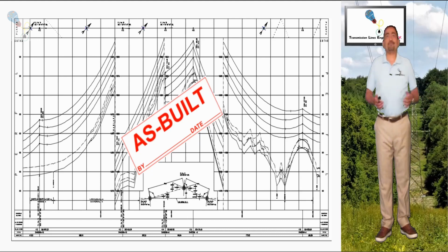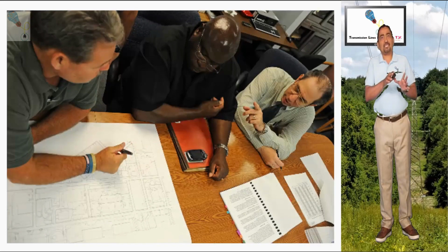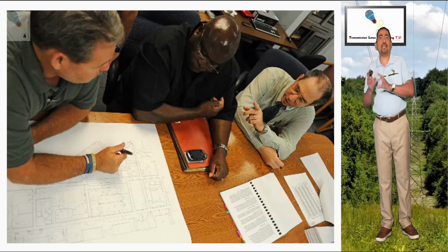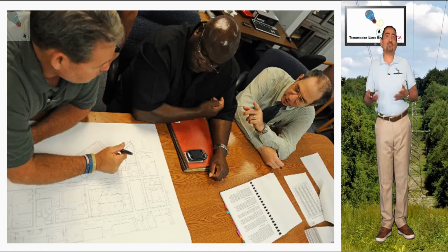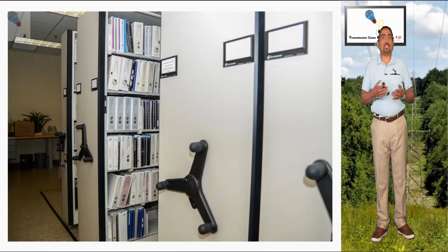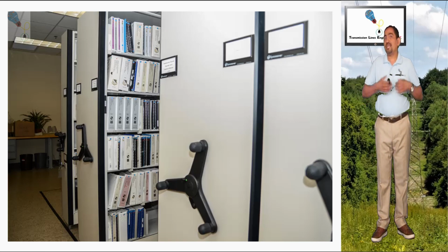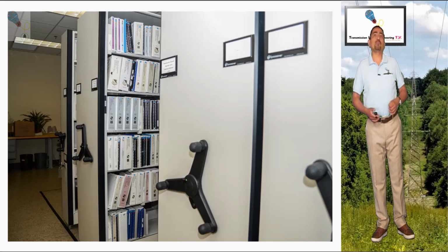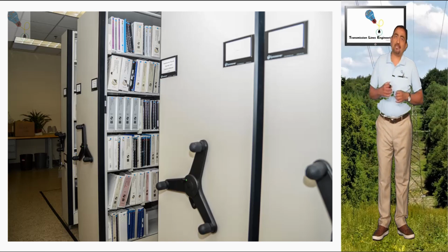Step 27. The quality areas will check that the areas of construction and engineering have the totality of the quality formats duly documented, and the quality package, which is the history of the project construction, including not only formats but visual references such as pictures of each structure, as well as cable installations, grounding systems, OPGW, etc. Step 28.